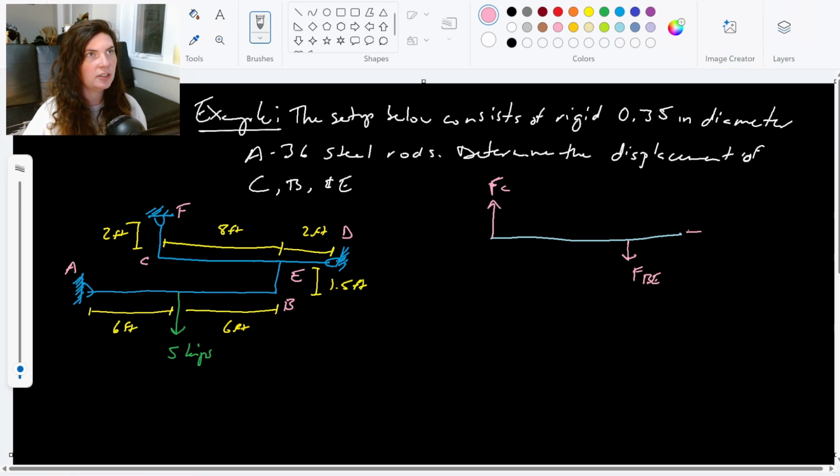And then there's that connection point at D. So I'll call that dx and dy. There are those reactions there. And we notice that we have this pin here that's allowing rotation. So the rods EB and FC are stretching, but it's pinned at point D. So what's happening is that because the stretching is being allowed, there's this sort of rotation that's occurring, not this dramatic, of course, because of the displacement in rods FC and EB.